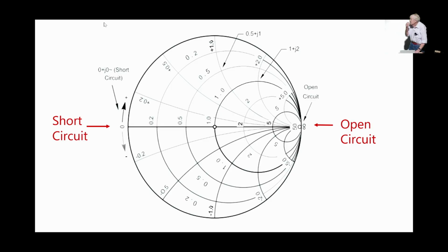But notwithstanding, we do deal with short circuit and open circuit as an example. And by the way, one revolution of that Smith chart represents 1/2 wavelengths. 1/2 revolution is 1/4 wavelengths. So there's the inference that a quarter wave from an open circuit, you might find a short circuit.